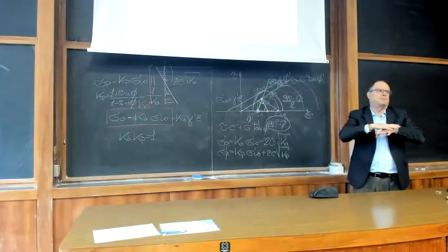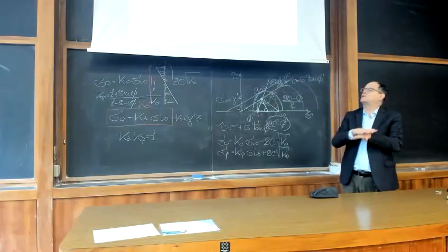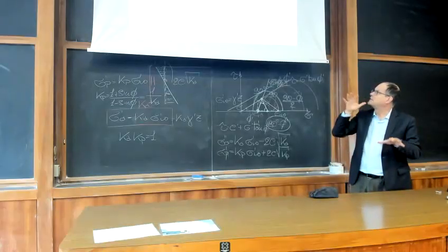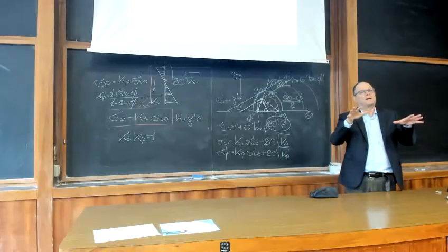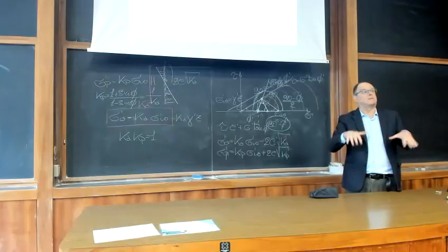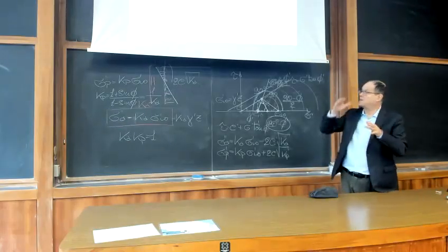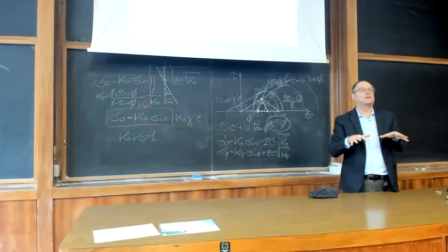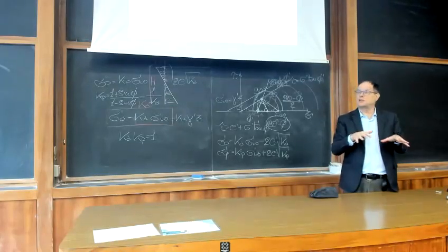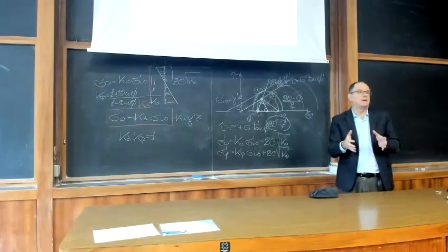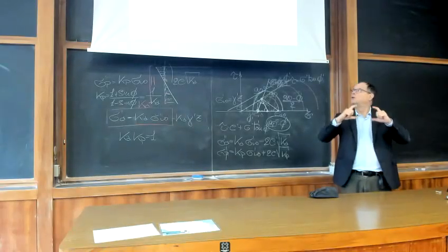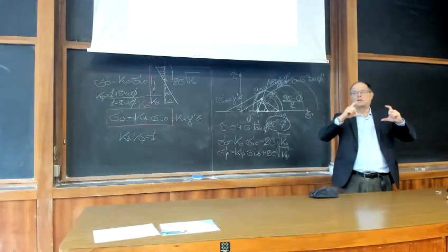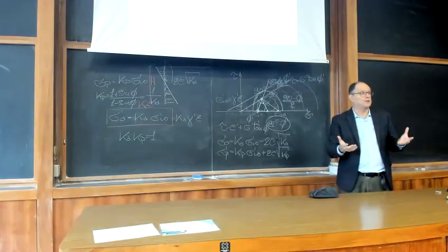First, because the ground surface is typically remolded, but mainly because it is subjected to climate variations. The soil can move just because there is a water content variation during the season, for example, from winter to summer, and the soil will tend to shrink or expand because of water content variations.